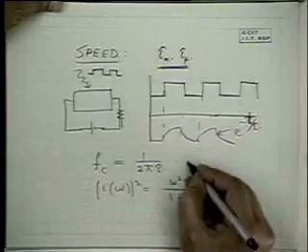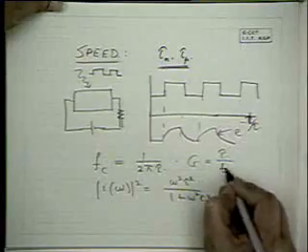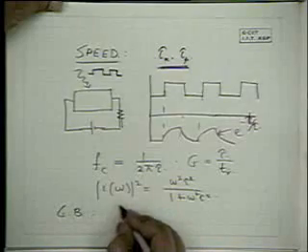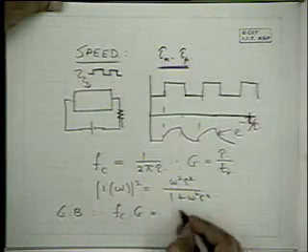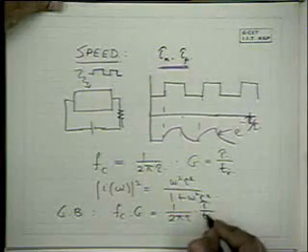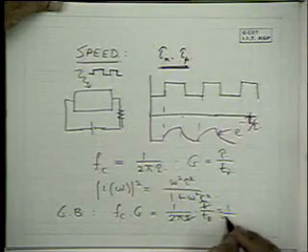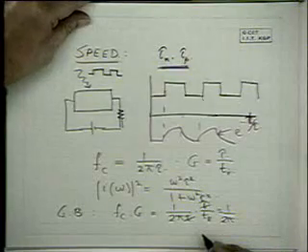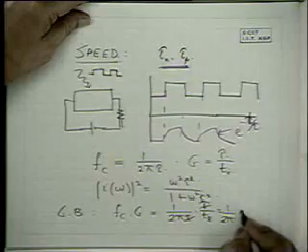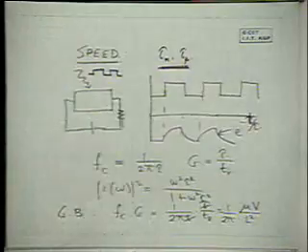We've seen that the gain is tau by TR. So the gain bandwidth product Fc into G is 1 by 2 pi tau into tau by TR. The taus cancel, so it is 1 by TR, and TR was calculated earlier, so this is just mu V by L squared. This is an important consideration,